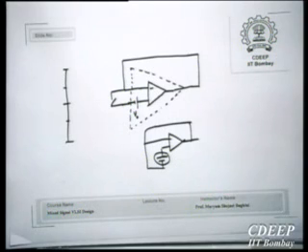You got that? Essentially the actual op amp is offset, its gain is 1. So if it is offset by some voltage, when the input is 0, the output will be the offset voltage. Not a big deal. Right now I am talking about differential voltages. The reference could be anything, then the output is also measured with respect to that. So there is a differential offset voltage between these two. If I measure with respect to the same reference to which the input is applied, then the output voltage is a measure of the offset of this.